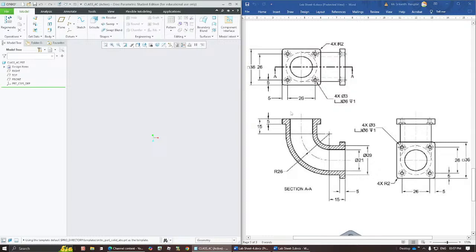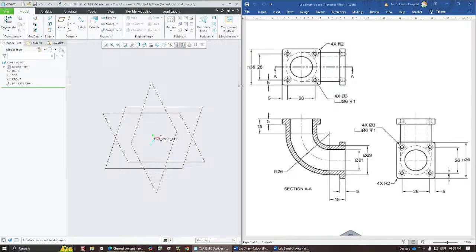So what kind of features are we going to use for this? You can see that the cross section is like a pipe, and there is a profile on which this cross section has to get extruded, or it has to sweep that particular cross section. So in such cases, we have a ready-made option here called the sweep. So in order to use the sweep, okay, let me get back on the planes first. I will create this like this.